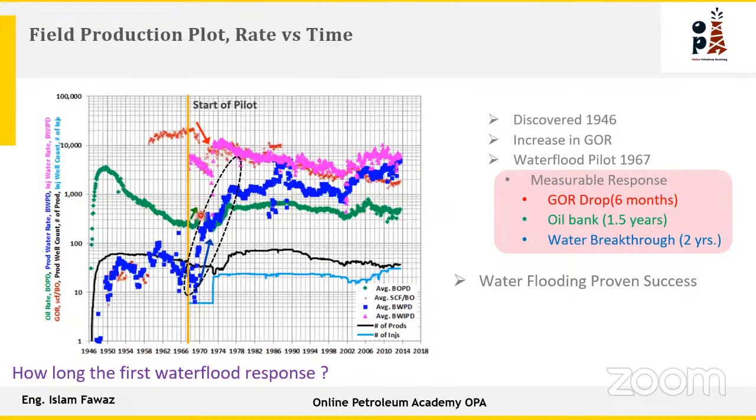The GOR dropped 6 months later. Oil bank is increasing after 1.5 years. Water breakthrough is after 2 years. So we have a response to water injection, yes, but the response is delayed, after 6 months and after 1.5 years of injection, showing the impact of the waterflooding.